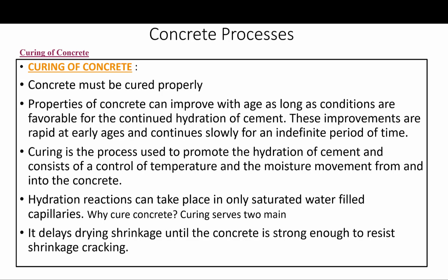Okay, curing of concrete. I couldn't emphasize this topic more. Concrete must be cured properly. Properties of concrete can improve with age as long as conditions are favorable for the continued hydration of the cement. And again, when we study cement hydration, you will appreciate this and understand why curing is so important. These improvements are rapid at early ages and continue slowly for an infinite period of time. Curing is the process used to promote the hydration of cement and consists of control of temperature and moisture movement from and into the concrete. The hydration reactions can take place only in saturated, water-filled capillaries. We will see what that means in the cement module.